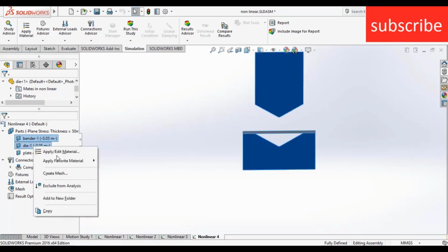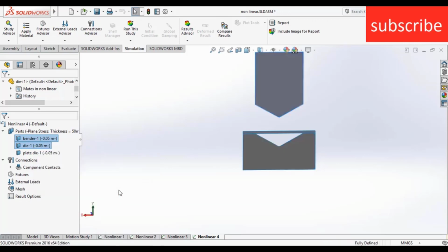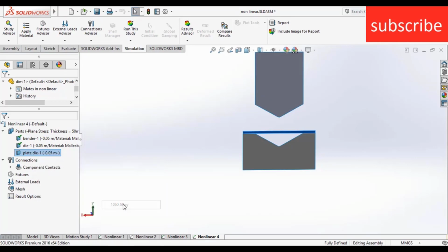Right click on it, click on apply favorite material. Select the material as per your requirement. For example, I select malleable cast iron. You can choose any other material as per your requirement, and the plate die as 1060 alloy. Remember, always select the plate material as something that can bend.